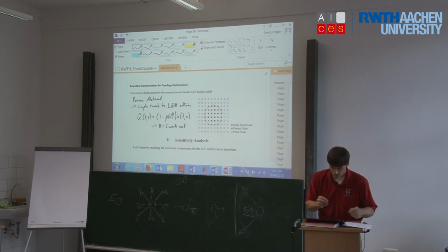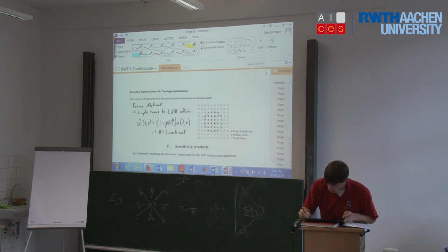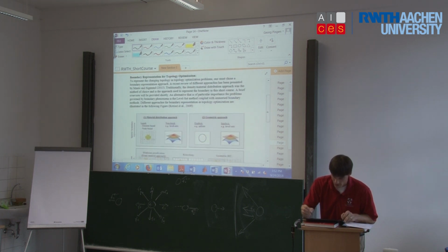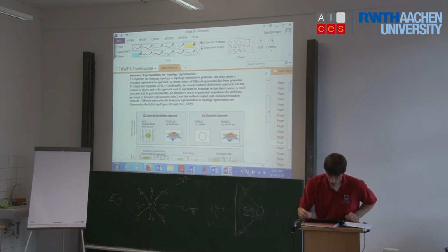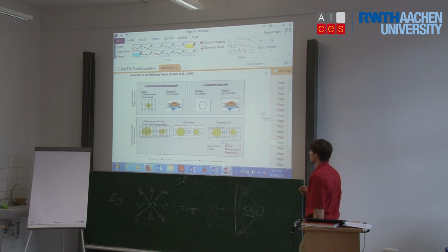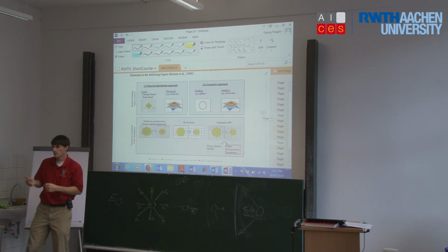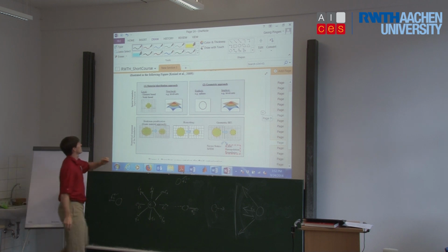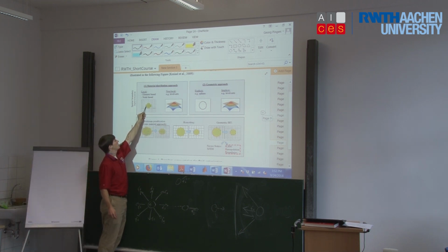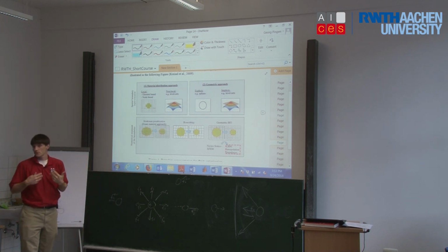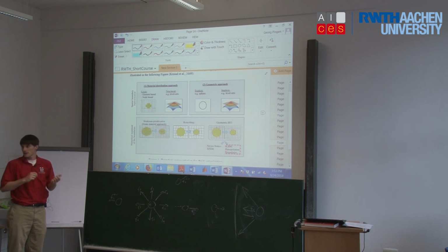Okay. So going back 2 pages. When we have topology optimization, and we briefly talked about this during the break, we have a couple different ways to represent our boundary. One option is to use this local, voxel-based or element-based, material-based representation, where at any point we know this point is either solid or fluid, and we have this regular grid. And what we can then do is use this Brinkman penalization, where we use this density idea, or this porosity idea, in order to represent the shape.